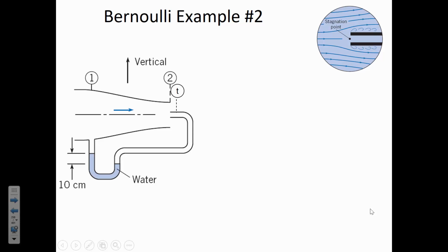This I'm going to call the pressure inside the tube. And what we mean is the tube that's receiving this stagnating streamline. And so on the inside here, P sub T in the tube is the same at the bottom and through all of the gas inside of the stagnation tube. But the pressure inside the tube is not the same as the pressure at 2. And think about it logically, the pressure between here, where the gas still has velocity, is going to be different than the pressure inside the tube.